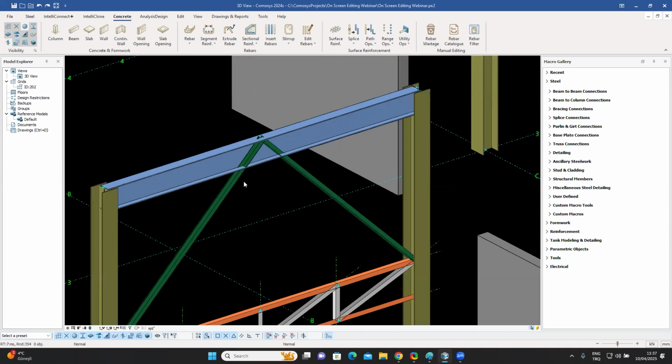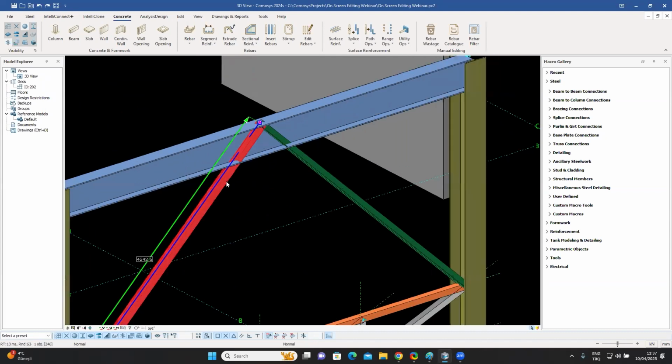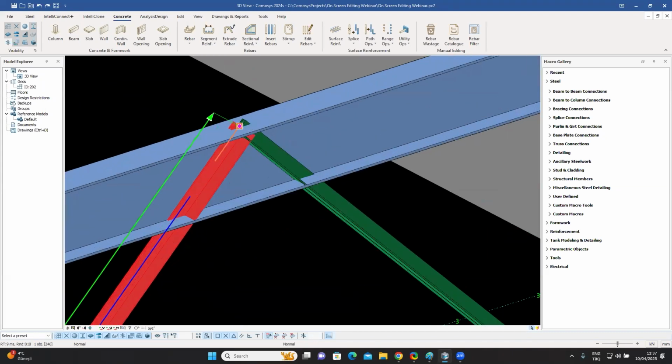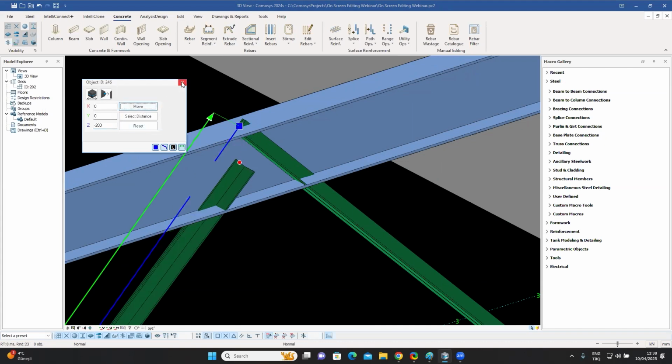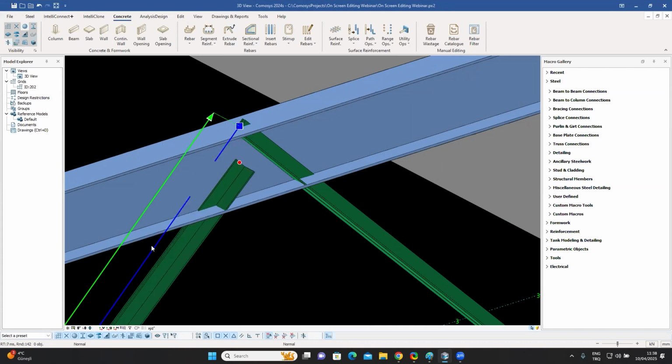to a desired location. Now for that, for example, if I select this one, if you remember, I chose the tail over here. But instead of the tail, if I go inside and select this one, the little circle inside over there, and now if I give it a distance of, for example, minus 200 in the Z direction, and if I say move, you can see that my frame element is still connected to the top, but the physical element has been given an offset.